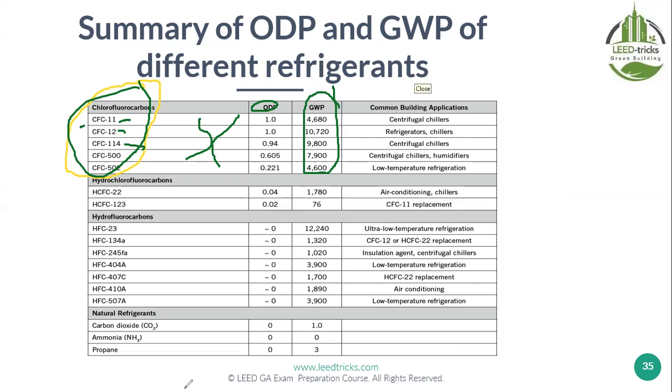No, no. HFC is here, hydrofluorocarbon, as you can notice, but it's not the best. The best refrigerants are natural refrigerants. We spoke about them in the first slide, like carbon dioxide, ammonia, and hydrocarbons like methane, propane, and so on. Remember? So this is the best, and this is the worst.